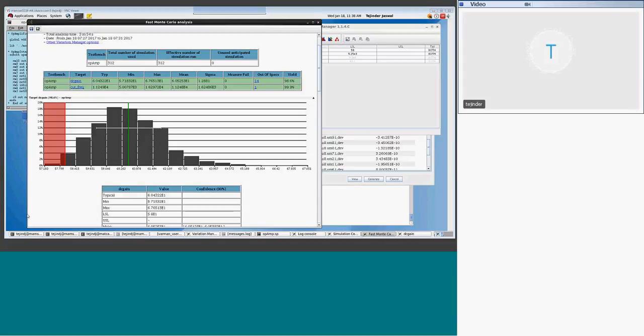We do this analysis in some ways, but the idea is really, instead of doing Monte Carlo everywhere, for example in the middle of the distribution, where these samples might not be very useful, we explore with a controlled budget. For example, you can say my budget is only 1,000 simulations, and I want to study the design to 3 sigma. So the Variability Explorer is more suitable for high sigma analysis. But you need to see it as Monte Carlo. That's it.